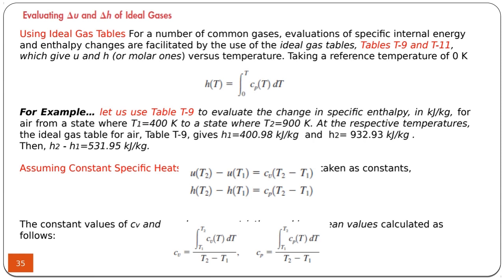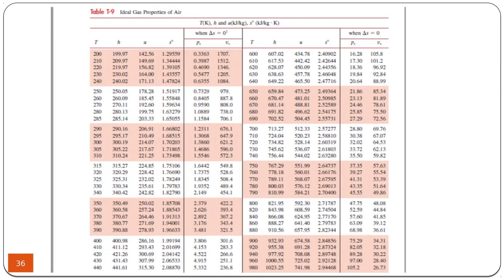Okay, these are some examples of enthalpies of air, because normally enthalpy is related to Cp and temperature, but this relation is not given anywhere else. However, by using this table, you can find the enthalpy change in a gas if the temperature has changed from, let's say, 200 to 290.